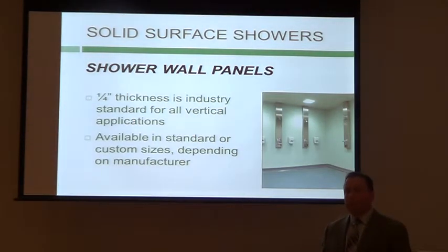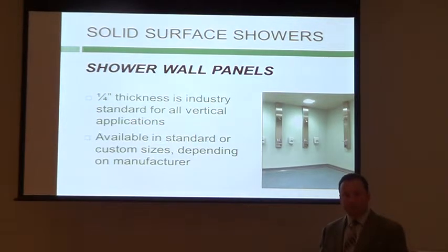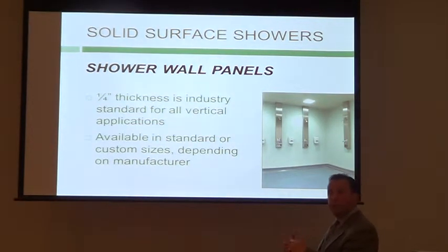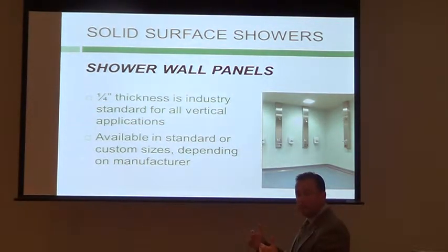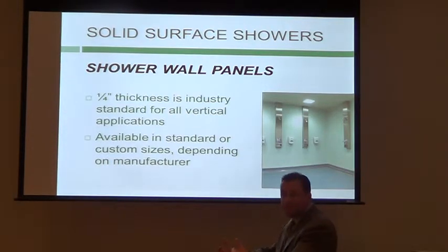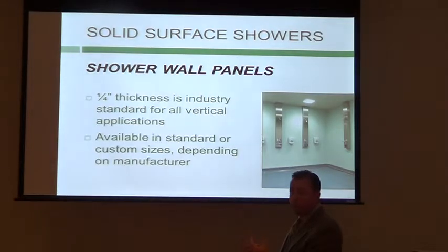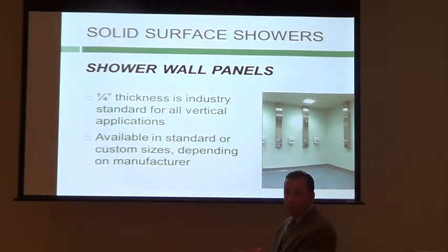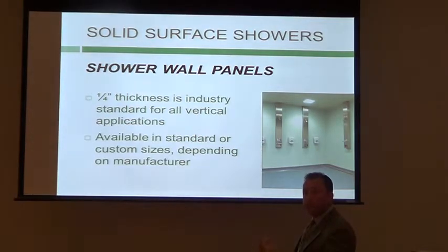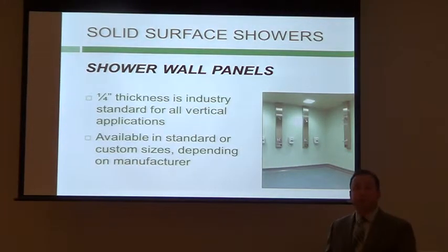But for most everyday commercial applications, a 1/4 inch is sufficiently strong because it's adhered to that wall with silicone. And that substrate, in today's commercial environments, is typically 5/8 inch thick cement board. Very strong. The silicone acts as tiny shock absorbers, and then I've got a polymer protective coating panel over the top of that. It takes a tremendous force to breach that. So very strong, very durable.